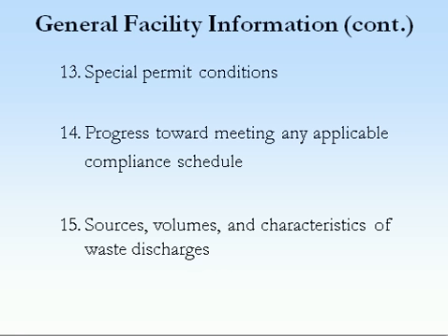Special permit conditions. You're looking for something like if there's a best management practice that's in the permit, or possibly it's a tiered permit, so that limits are different during different seasons. Be aware of that before you go. If they're on a compliance schedule, you need to see where they are progressing towards meeting those timelines. Is there a date coming up soon by which they need to meet part of that compliance schedule? Just being aware of this will help you ask important questions while you're there.